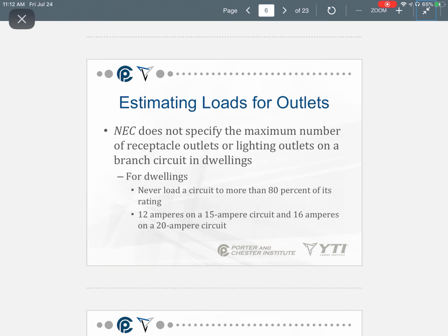So they've determined that the recommendation is a maximum of 13 receptacles on a 20 amp circuit. And that's where that comes from. It's based on 1.5 amps per receptacle, or 180 volt-amps per receptacle. So they've rounded it off to 13 receptacles as the recommendation. It's not a rule, it's a recommendation.